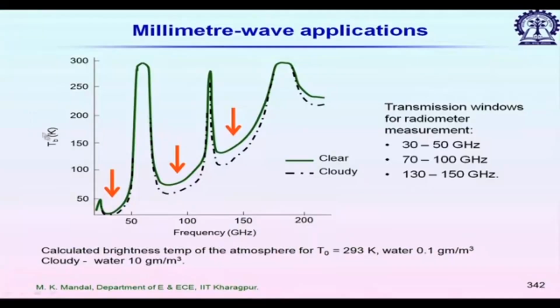Now when we go for actual design, we can't use any arbitrary frequency range. We have some atmospheric windows, and we have to use those frequency bands only. Why? Let us say the 60 gigahertz band. Oxygen molecules resonate at the 60 gigahertz band and re-radiate, so the brightness is already very high and we will not have good contrast. For imaging we also need good contrast. So we have an effective brightness variation versus frequency.